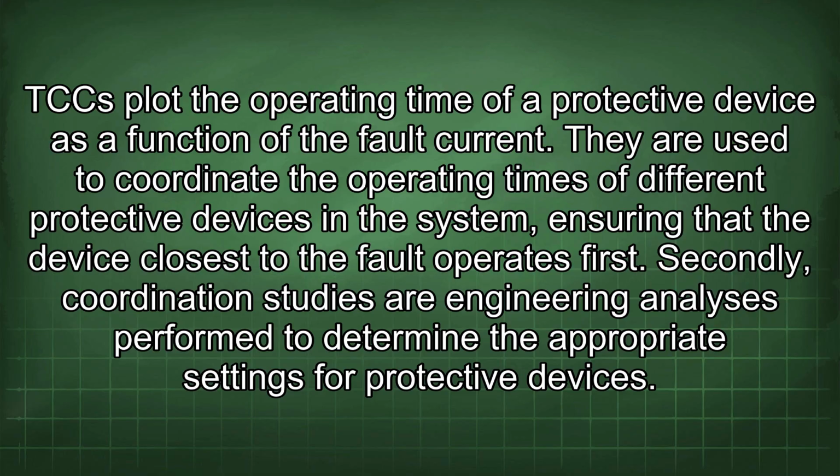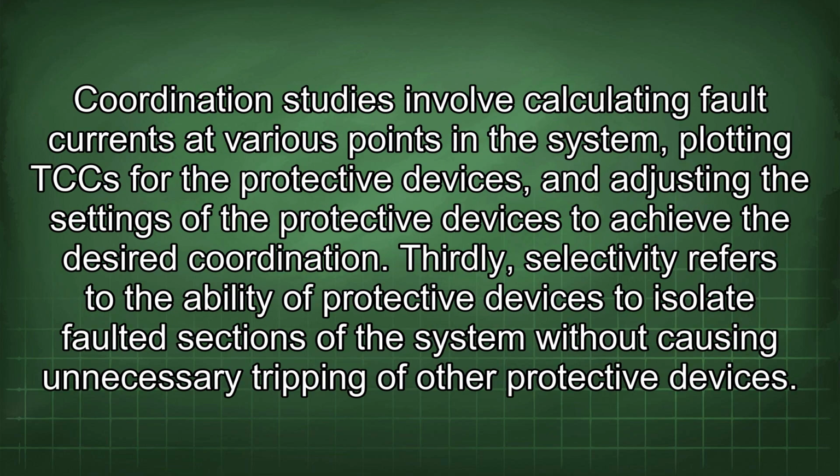Secondly, coordination studies are engineering analyses performed to determine the appropriate settings for protective devices. Coordination studies involve calculating fault currents at various points in the system, plotting TCCs for the protective devices, and adjusting the settings of the protective devices to achieve the desired coordination.